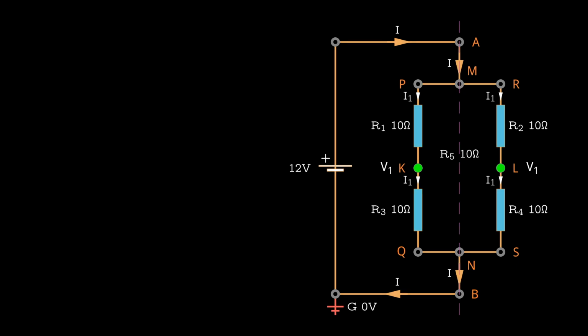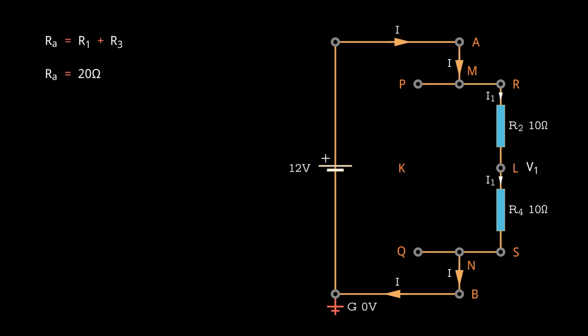We will remove the resistor R5, and continue tracing along the two parallel paths, stopping when we reach the end of the resistors. This process simplifies the circuit by reducing the number of resistors, without altering its characteristics, making it easier to clearly identify the series and parallel resistors. To calculate the equivalent resistance of the circuit, we start by simplifying the resistors that are connected in series. For resistors in series, their equivalent resistance is determined by adding their individual resistances together.